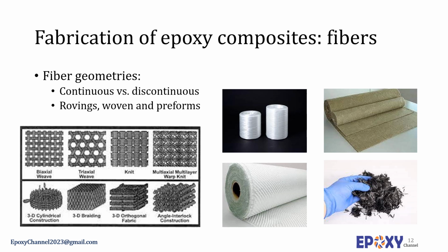The form of the employed fiber reinforcement is determined by the fabrication process. Discontinuous fibers allow complex moldings to be manufactured rapidly. The fiber length is generally less than 5 mm in molding processes. It should be noted that a critical fiber length exists below which the reinforcing efficiency is seriously reduced. Generally, the critical length of fibers in thermosets is larger than that of thermoplastics.